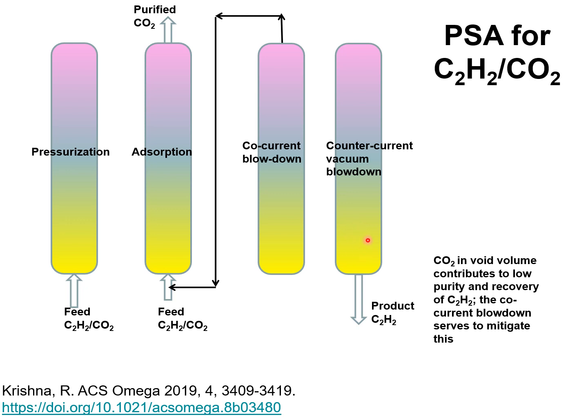Any CO2 that is remaining in the void volume and inside the pores will contribute to lower purity of the product. In order to achieve high product purity at high recoveries, it is important to choose an adsorbent material that practically rejects CO2 entirely into the gas phase and does not adsorb CO2 at all.